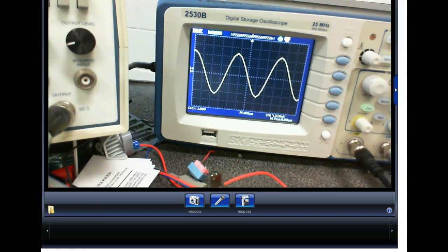So if we have problems with electromagnetic interference, or problems with our power supplies, I can measure that, and we'll try to do that. We think power supplies are nice and beautiful, but every one of them has a specification called noise or ripple. If you get outside those ranges, noise on the power supply is a real problem in digital, because in digital everything's turning off and on, right? You're putting constantly different loads on your power supplies all the time. So you get this switching noise on your power supply, which can cause all kinds of problems. You can't see that with a meter.